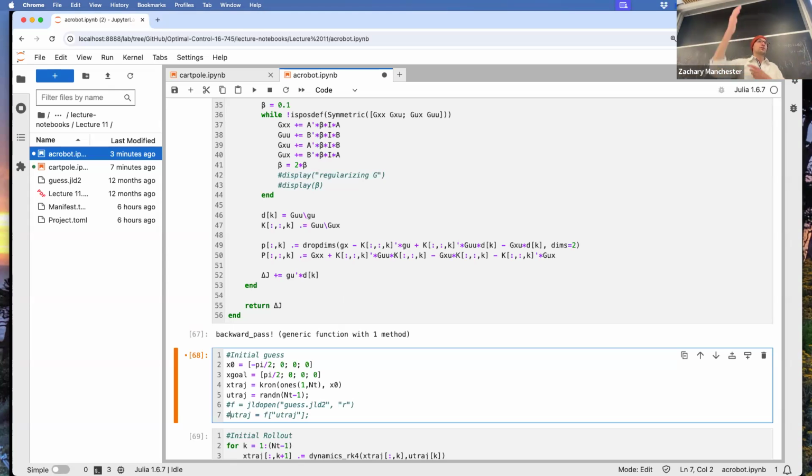So what you could do, for instance, is this: there's two angles, right? And you want the velocity to be 0. So I would set this one to be something arbitrary, like say 10 degrees. And then I would use Newton's method to solve for the shoulder angle such that X dot equals 0, right? Then you plug that in as your goal state right here, and you'll swing up to that. And then you can wrap that in an LQR balancing controller once you get to the top.